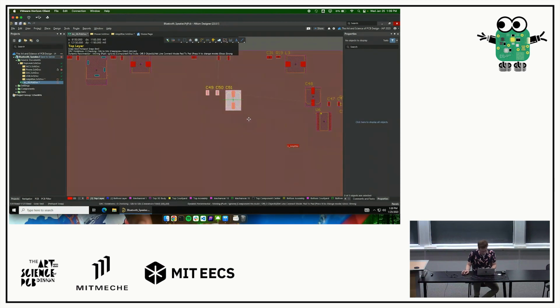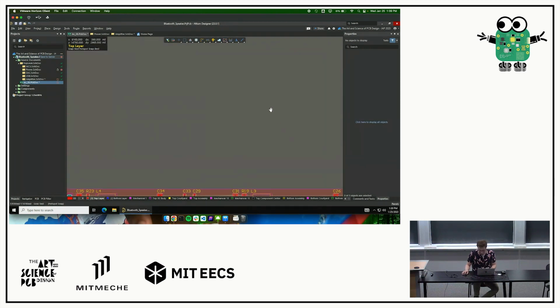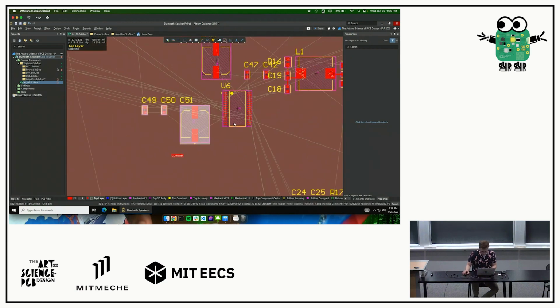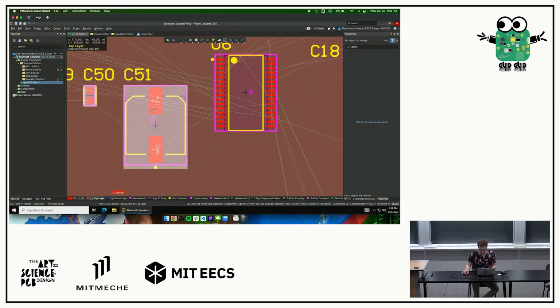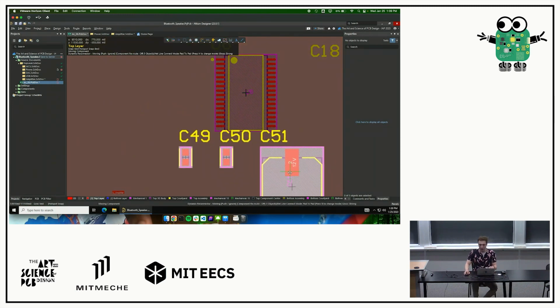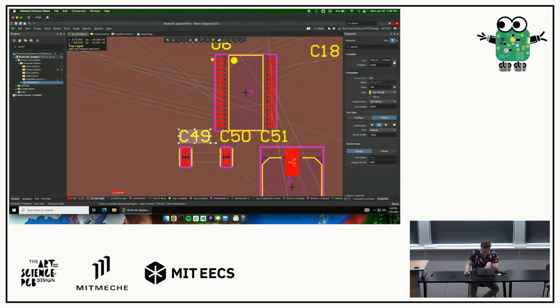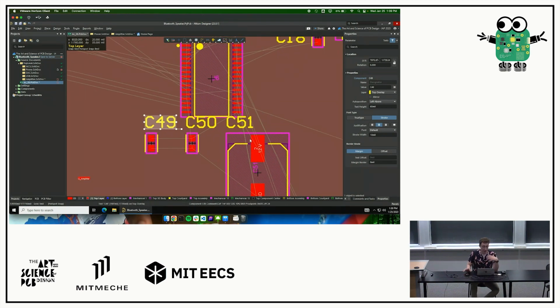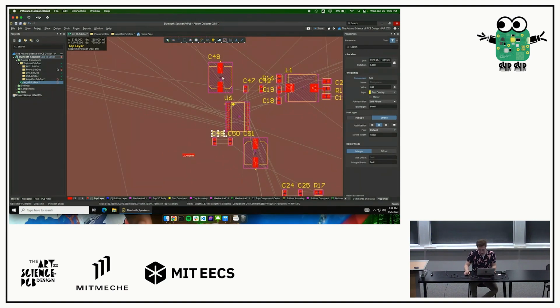Okay, so we'll just grab these. And then, again, we want 12 volts to be near the chip. And we notice, okay, 12 volts is the pad up there. We'll take this and then just drag it over there. Again, I don't really care right now that the silk screen is colliding with everything. That's easy to fix later. What we care about right now is that our rat's nest gets tamed. We want that to be nice and less complicated so that our routing is easier to do. Cool. So there's our bypass caps roughly set.